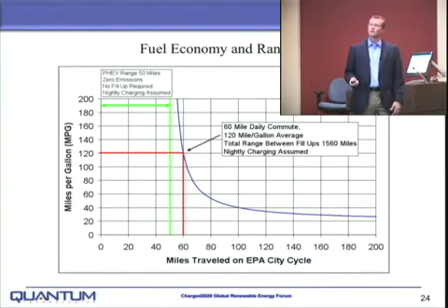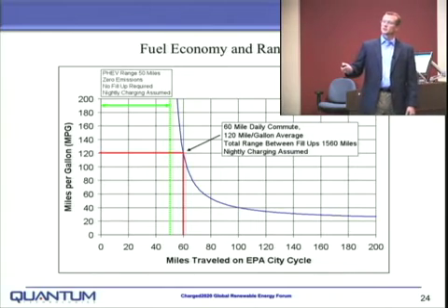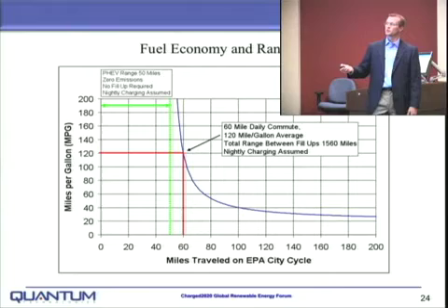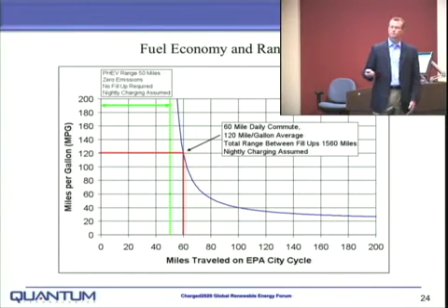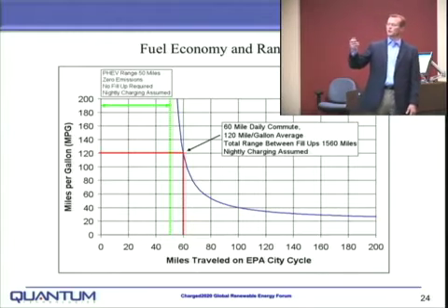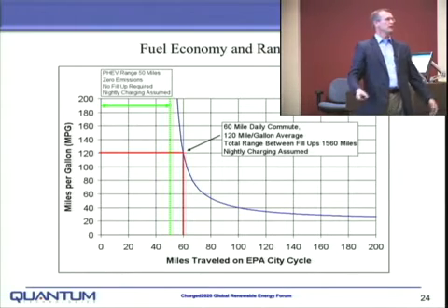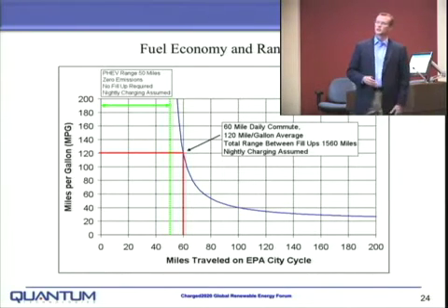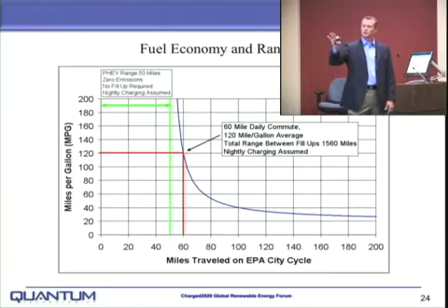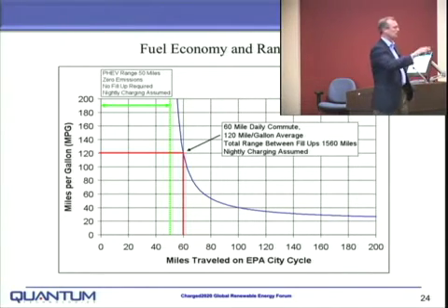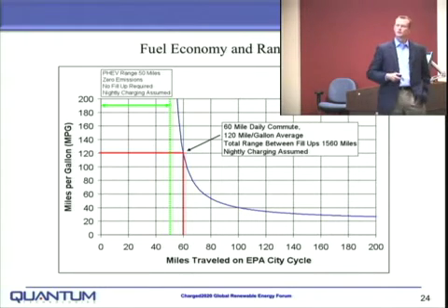That sounds great. What happens if you go 70 or 80 or 100 miles? Well, now you drop down, you come down this curve fast. At some point, you become constrained by the fuel economy of the base engine. So when you hear these wild claims about the fuel economy that a PHEV will get, they're typically using this kind of analysis: well, I went 52 miles and I'm getting 200 miles to the gallon. That sounds fantastic, but it's a bit misleading. So it's just a little bit of a primer: next cocktail party when somebody's talking about their PHEV, you can quiz them on that.